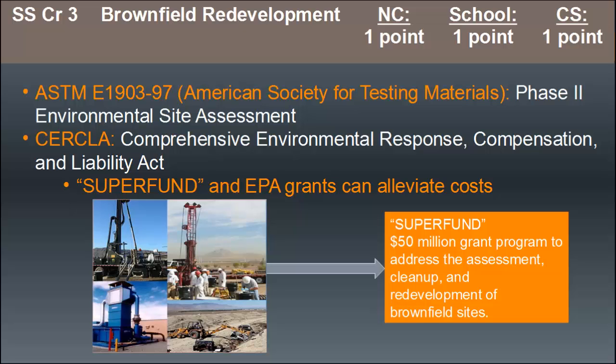There are 3 different ways to remediate a brownfield. One is ex situ, which is the least preferred. It occurs at another location, typically a treatment facility. It's a pump and treat system using carbon filter and incineration. More advanced version of this is chemical treatment or biological.